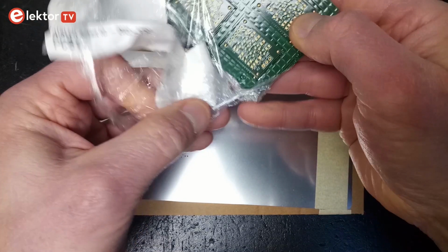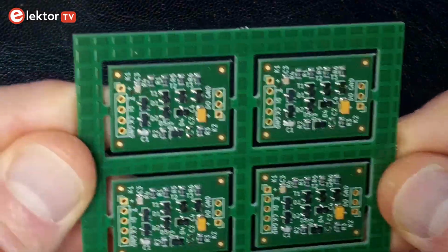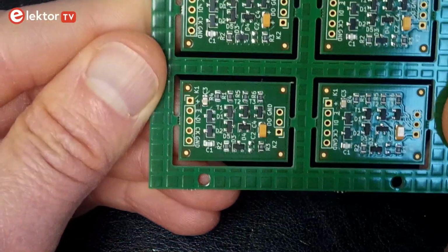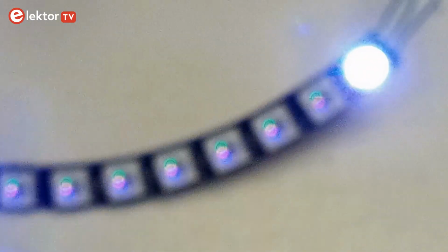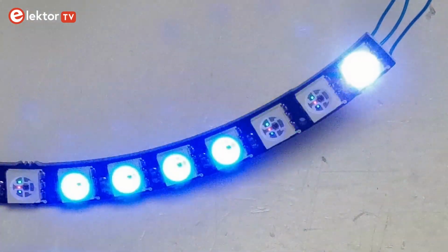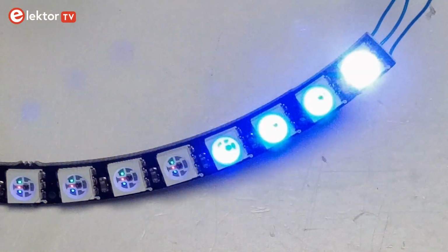A few days later I received the PCBs. Since the circuit is small, I assembled 4 boards to see if spread in component values might have any influence on the way it worked. The circuit turned out to work fine for SPI modes 0, 1 and 3. In mode 2 it still works, but the first pixel is always bright white, while the others won't switch off completely. This is due to the SCK and MOSI signals both being high when idle in this mode.